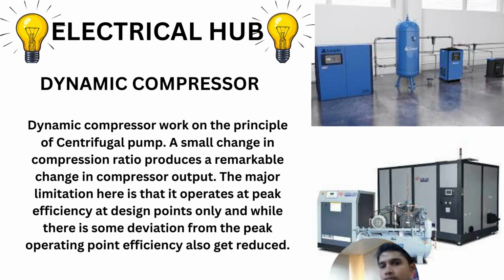A small change in the compression ratio produces a remarkable change in compressor output. The major limitation here of the dynamic compressor is that it operates at peak efficiency at design point only. And while there is some deviation from the peak operating point, efficiency also gets reduced.